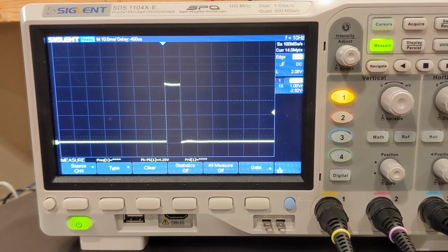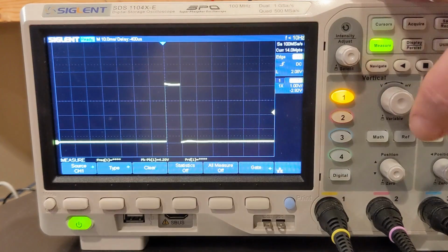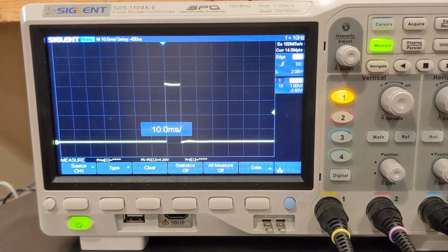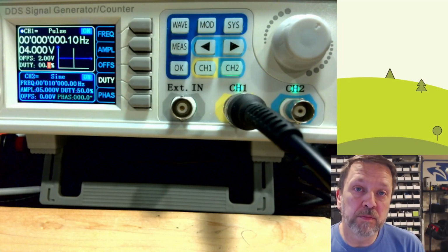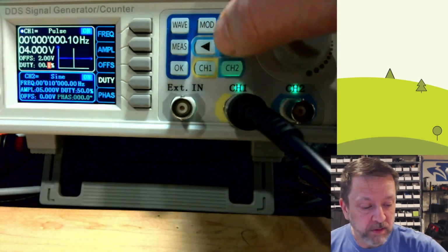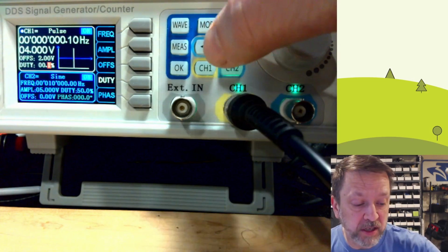So there we're getting a pulse that goes high one time. It is, what did I say? 10 milliseconds? Yep, 10 milliseconds long. And we get one every 10 seconds. Now, maybe your button works differently and it's always high and you press the button and it goes low. That's simply just inverting the duty cycle.